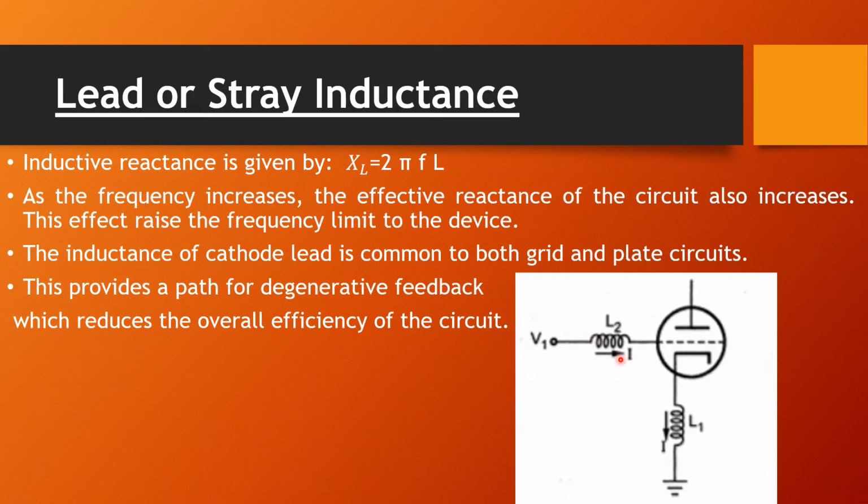This inductance is not actually connected physically here, but because of the frequency, the resistance of the device, and the physical characteristics of the wiring, it is induced in the leads. Such inductance is called the lead inductance, and with increasing frequency, its inductive reactance also increases.